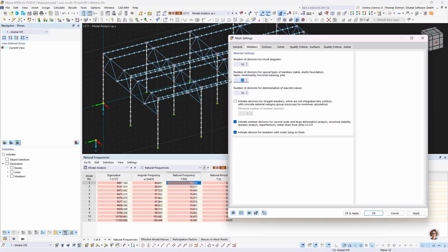And I'm gonna take it simple. I'm gonna just pick one here. I'm gonna leave this option on. That's perfectly fine. And with that, we will get rid of our plenty of in-between FE mesh nodes. It's also to be said, as you can see, only the beam members have those mesh nodes. The truss members do not. So internally in the program, we already implemented to simplify those truss members by 2 points, since it's just not needed to have more, also for static analysis.